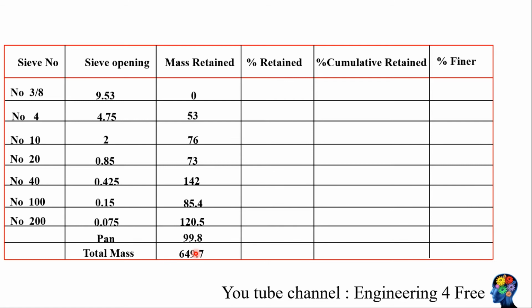To calculate percentage retained, you take the mass retained divided by the total mass multiplied by 100. For number 3/8, you have 0 divided by 649.7 multiplied by 100, which is 0. For number 4 sieve, 53 divided by 649.7 multiplied by 100, you will get 8.2. You will do the rest of the sieves in similar fashion.